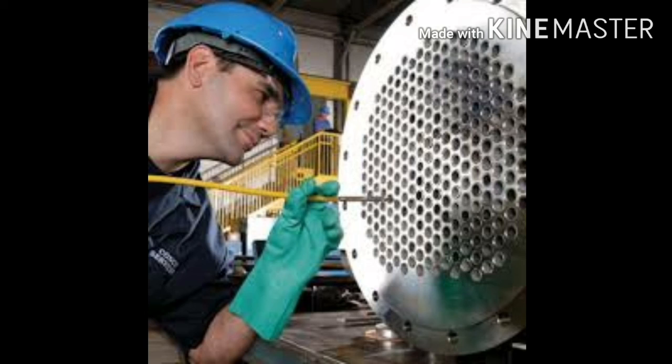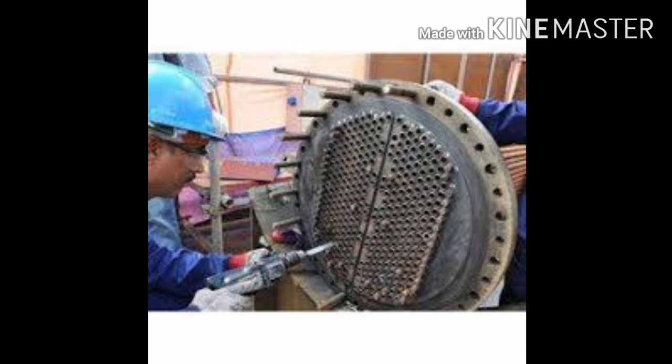I remember when I was in Isuzu, if the machine had a trouble, only the maintenance section could operate that. They have an ID. There is a stop switch that they attached on their ID, to let the operator see that the machine is already in maintenance or preventive maintenance, to secure that the machine will not operate.